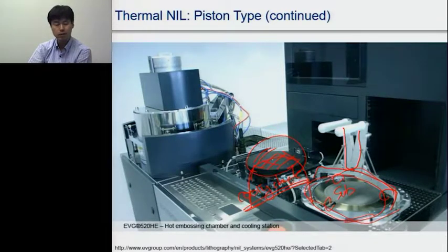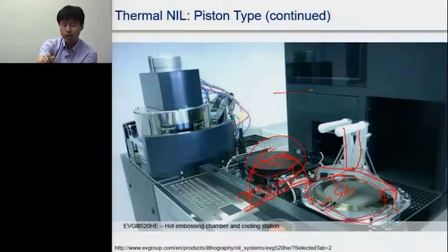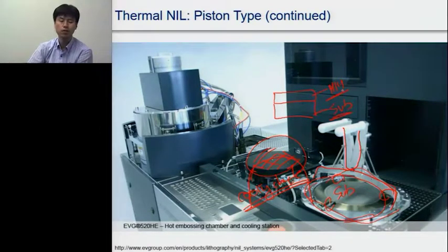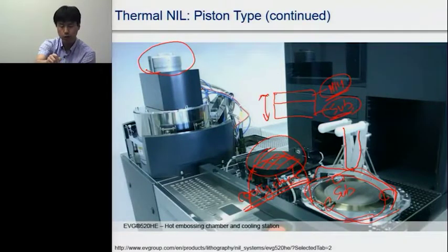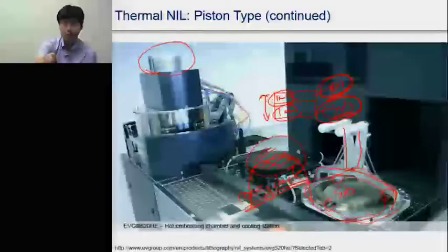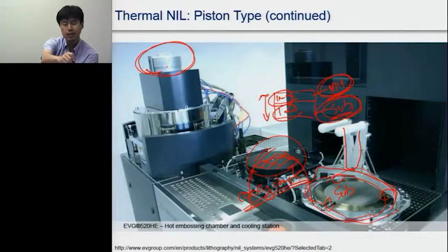Another interesting point is when you have a very thick master mold and substrate, the system does not know what thickness of the master mold and what substrate thickness we're going to use. So here is the ruler calibrating the thickness of the master mold and the substrate. If this is 1 millimeter and this is 1 millimeter, then we adjust the total height to 2 millimeters over here.